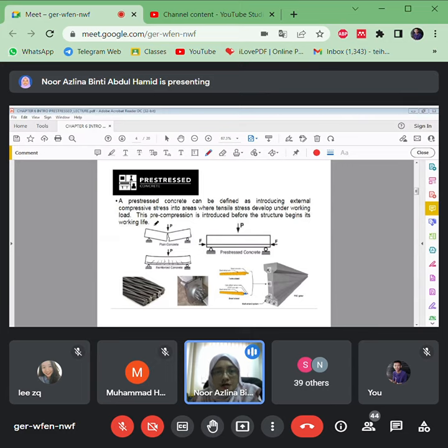If you look here, this is the plain concrete without any reinforcement. Look at how it deforms, deflects, and cracks. The cracks start from the bottom up to the top, so once we don't provide any reinforcement, it can split into two components.